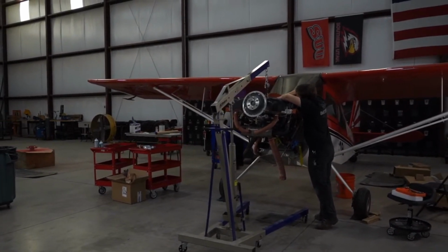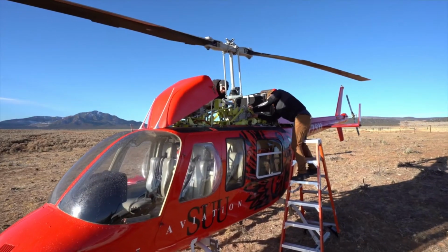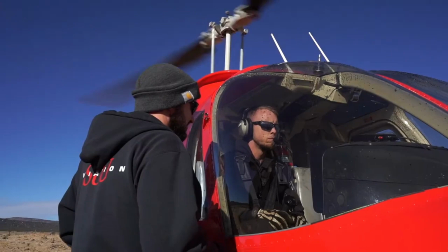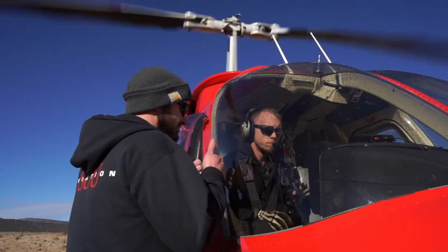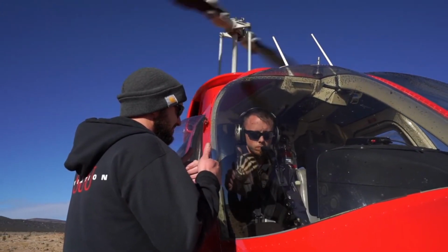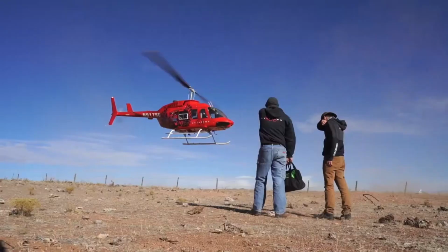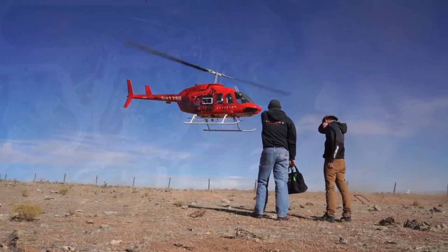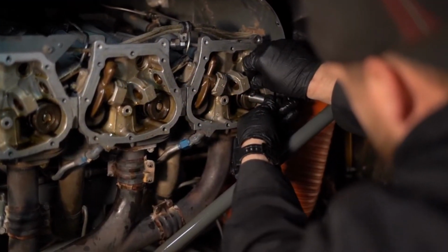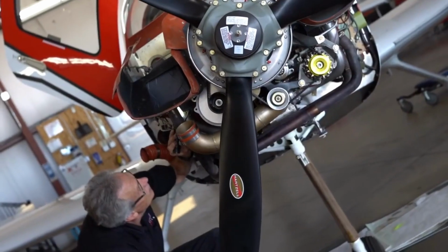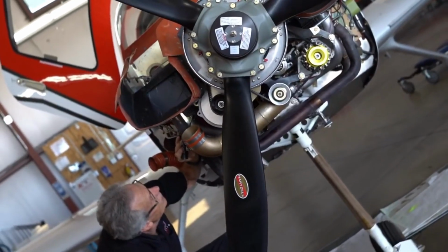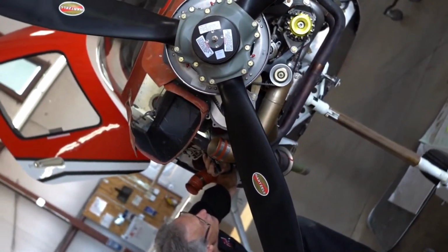Pilot of a helicopter, when operated under 14 CFR Part 135 and in remote areas, may perform specific preventive maintenance actions. These actions may only be accomplished under the following conditions. 1. The mechanical difficulty or malfunction occurred en route to or in the remote area. 2. The pilot has been satisfactorily trained and is authorized in writing by the certificate holder to perform the required maintenance.